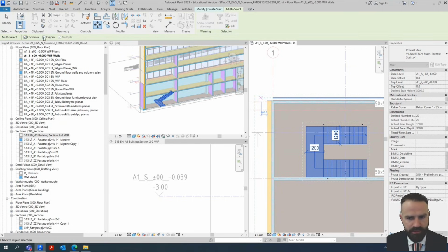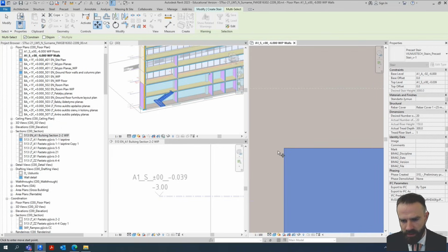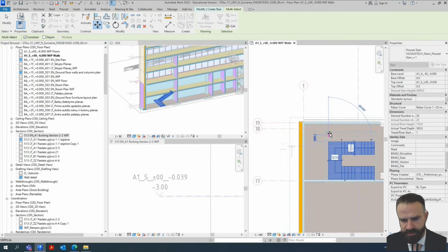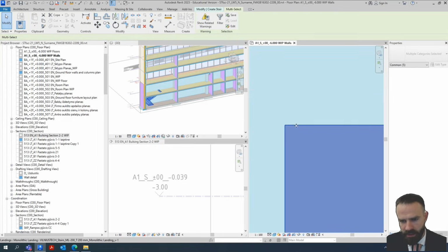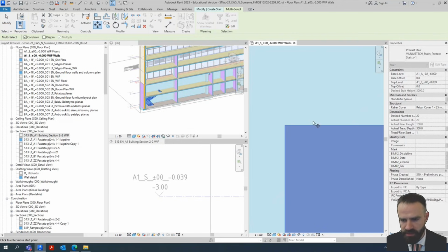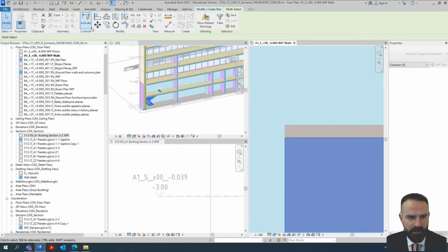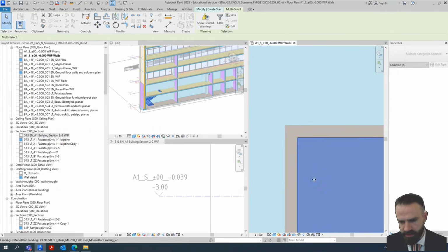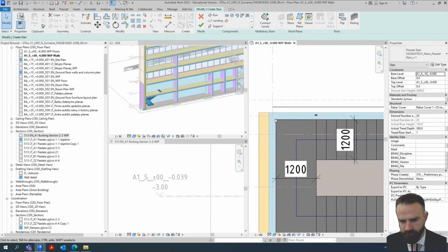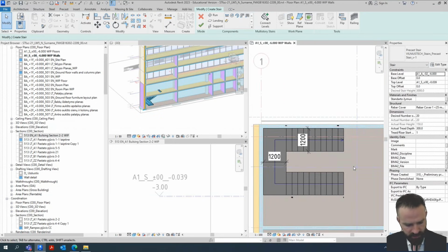Pay attention to not use this join tool. I select the corner of my stairs and move it to the side, can click shift and it snaps to the wall. And in here I should move the stair elements a little bit from the walls, as I mentioned regarding insulation for the sound. So I move it by 10 millimeters from the walls, or by 20 millimeters, depending on technology, how the stairs will be created.